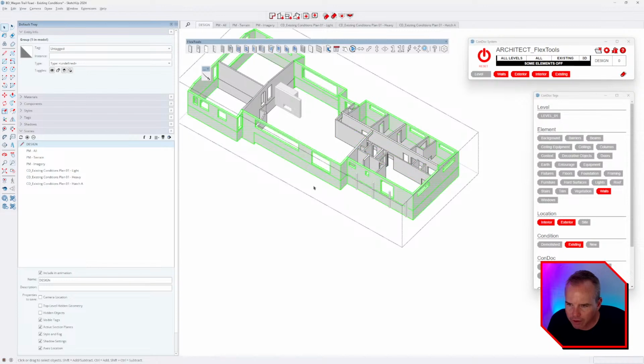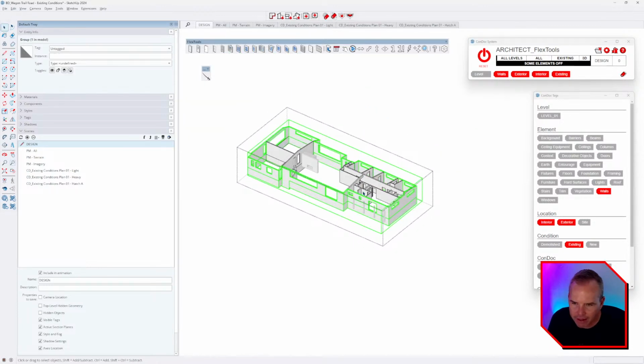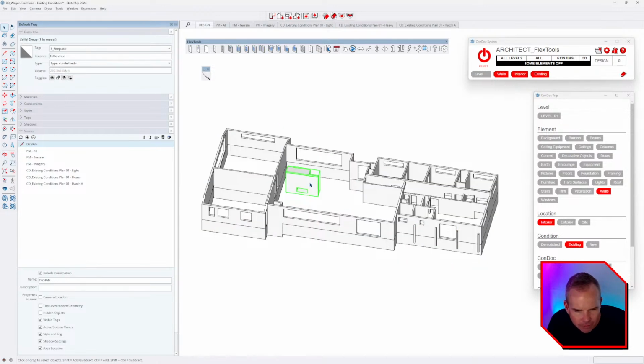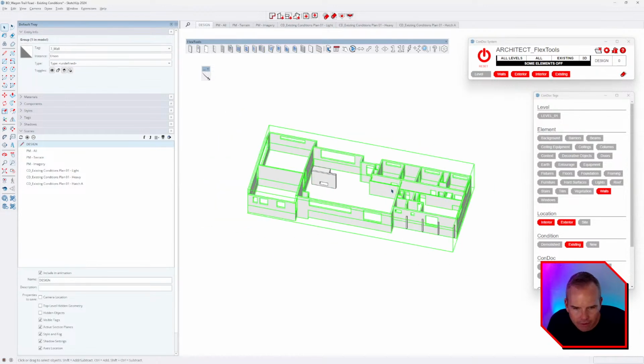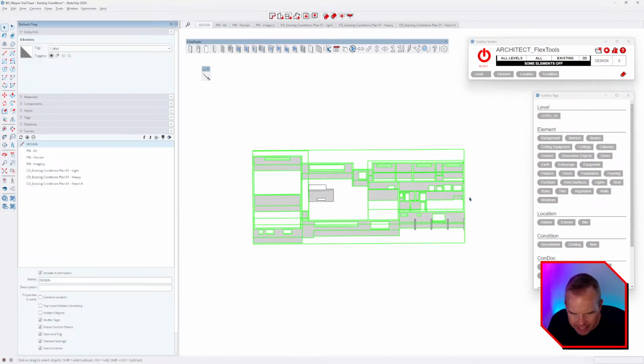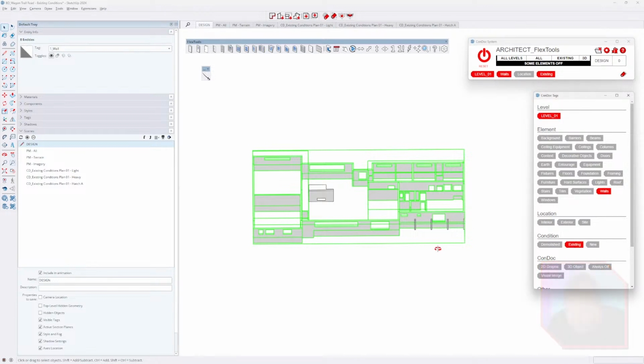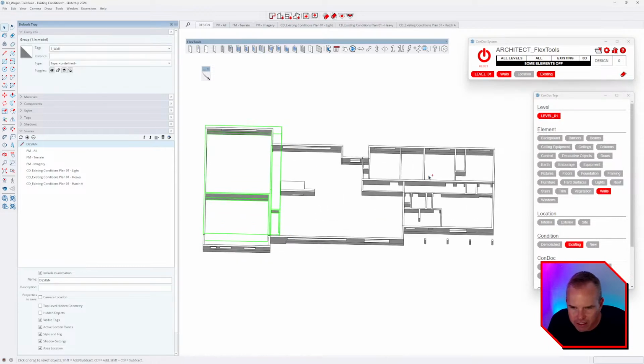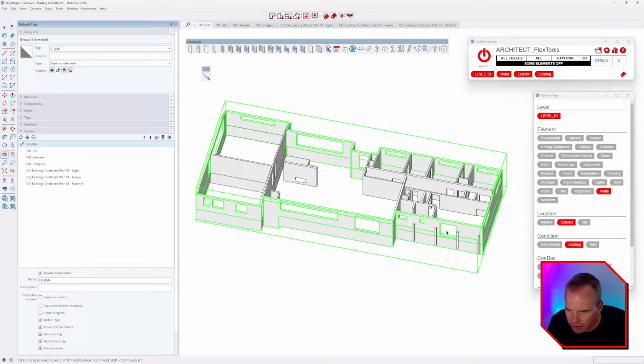And then we're going to triple click all this stuff and group that. And then I'll back out one. Those are walls interior. These are walls, and let's just explode this group. That way now I can retag this stuff as level 1 walls and existing. And now we're going to decide that this stuff is on the interior, so we'll just retag everything interior. This is all exterior. Now we've successfully sliced all those walls with our Zorro tool.